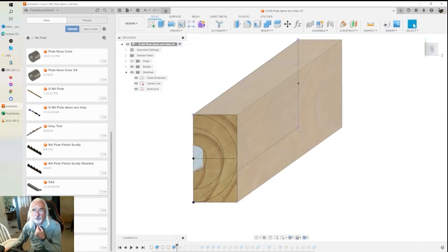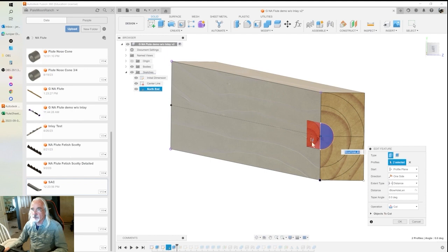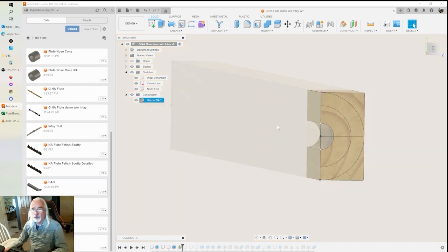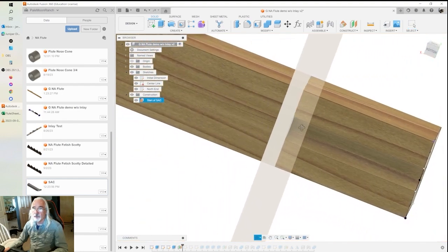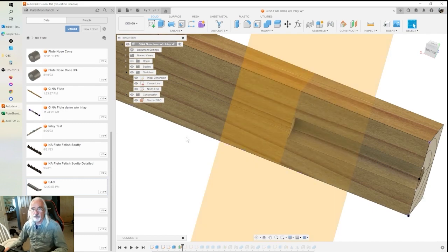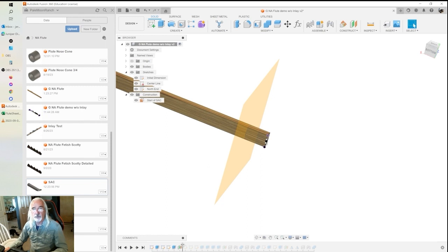First thing we'll do is extrude the blowhole. So it's a negative blowhole length to extrude that. Then I'm going to put an offset plane in here, at the end of that blowhole, which is the beginning of the slow air chamber. I'm going to need that in a little bit to cut in a space so that I can get a joint on this surface to put in my cutting tool. That'll make sense when I get there in a minute. Let's turn off that plane for a minute.